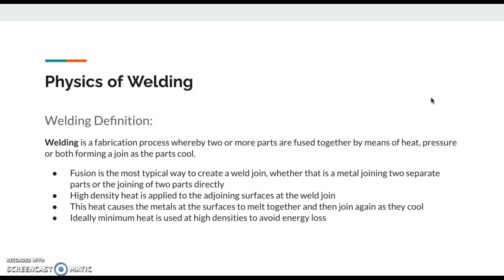Again, the definition of welding is this fabrication process whereby two or more parts are fused together by means of heat, pressure, or both, forming a joint as the parts cool. And essentially what that means, as it's pretty clear, I think, from the definition, you're getting something really, really hot until it gets to a liquid phase, so it's no longer a solid phase, that allows the two materials to combine with each other as they flow, and then once they've cooled, they form a stable joint.